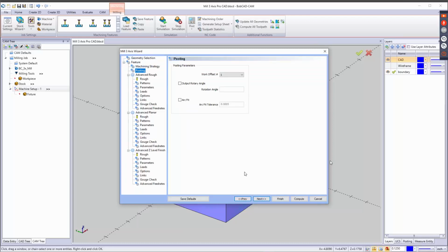So with the Pro Toolpath, not everybody here will have the Pro Toolpath. They give you a lot more control, a lot more tool options also, instead of just ML Rough, ML Finish, like the standard Toolpaths do. So there's a lot more information that goes on in here. I'm going to try to make this as basic as possible so you can get an idea.